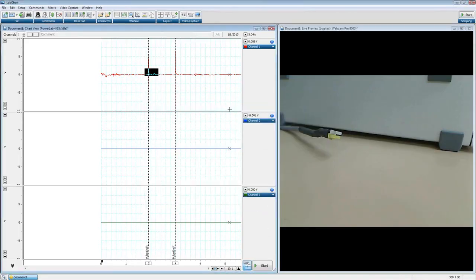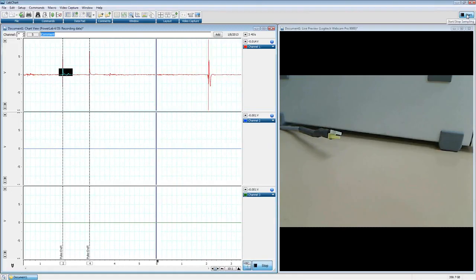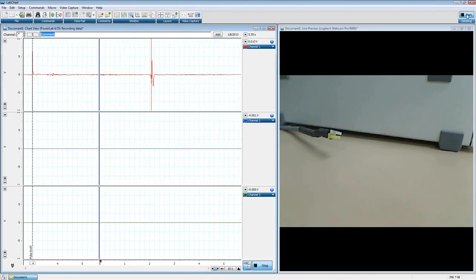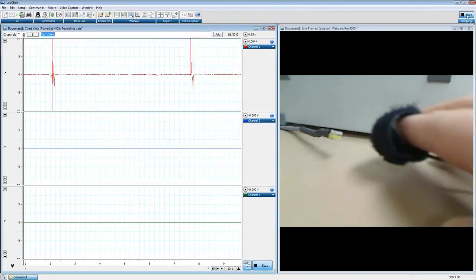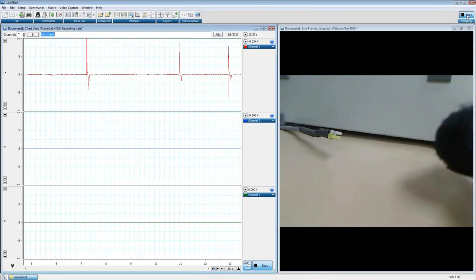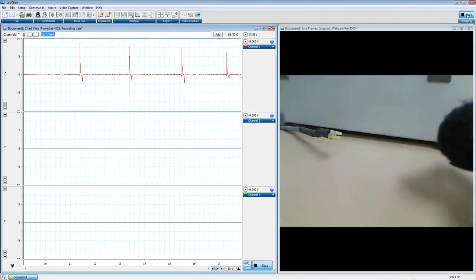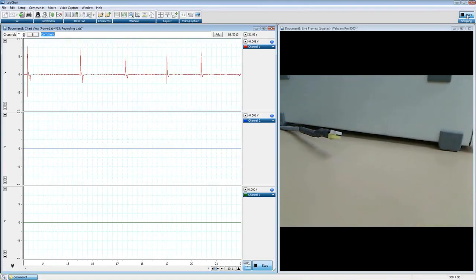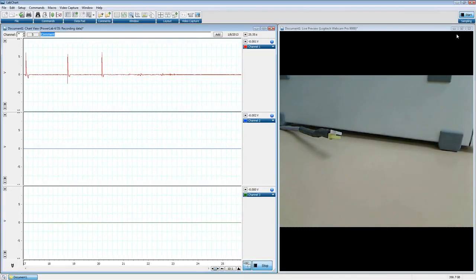Hit OK. And you'll see, turn it on, be very fast. We get our flashing light there. So go ahead and watch my recording there. Tap. Oops, let's try not to tap. We get our little LED light there. Like I said, very, very fast. It's all occurring in the hardware. So those are just the basics of fast response output.